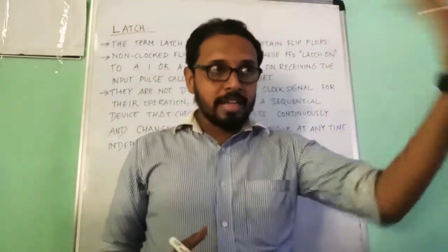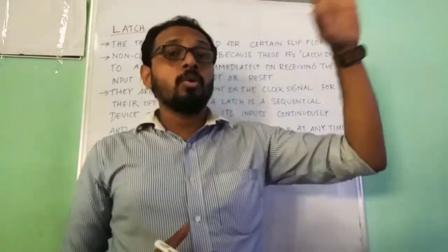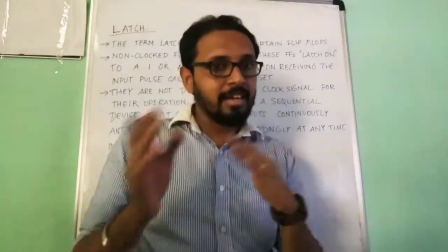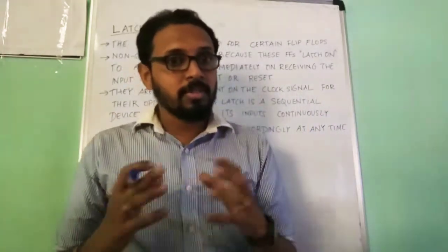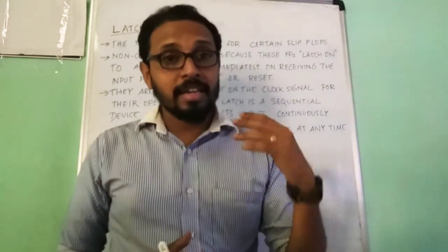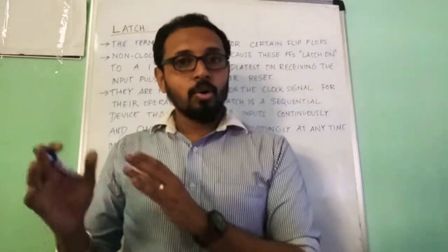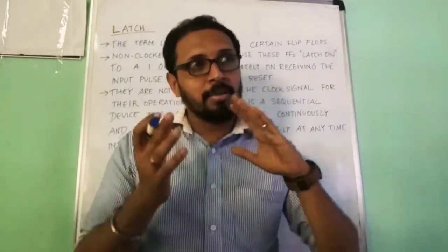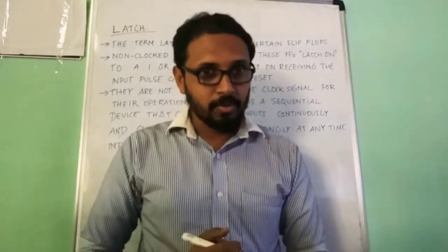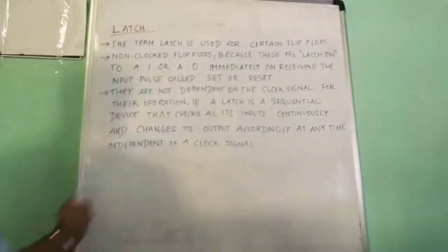But in the next topic, we will be discussing the gated latch or the clocked flip flops. Gated latch and clocked flip flops are the same. In the case of gated latch we will definitely have a pulse, but that is not a clock pulse. We have a pulse similar to the clock pulse, and that is called the enable signal. The details I will give you later, but for the time being let's discuss what a latch is.